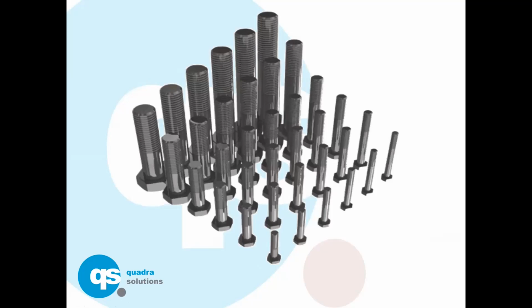But anytime you use one of those iPart children, you get another file on the hard drive that's got to be managed. As an individual driving the system, you only ever place the bolt iPart factory and you pick from a list. You don't know that all these files are being created in the background, but the fact that they are being created means something's got to manage them. So Vault will look after them, Inventor will look after them, but you've got more stuff on your hard drive to deal with.